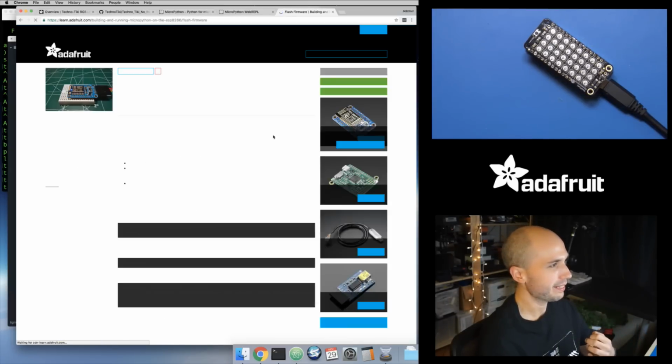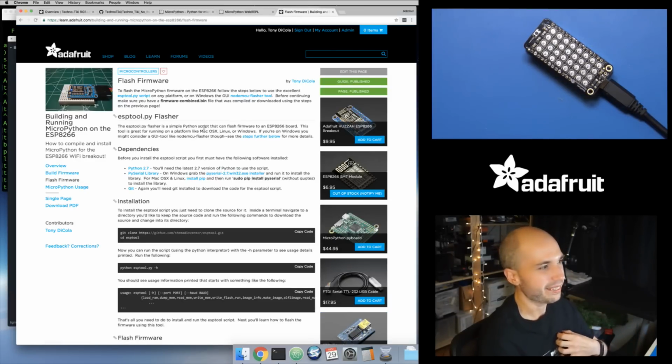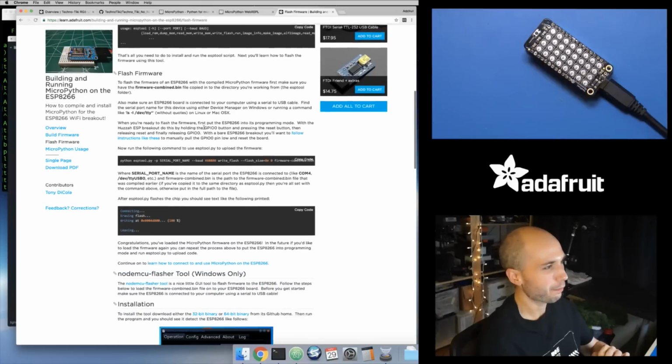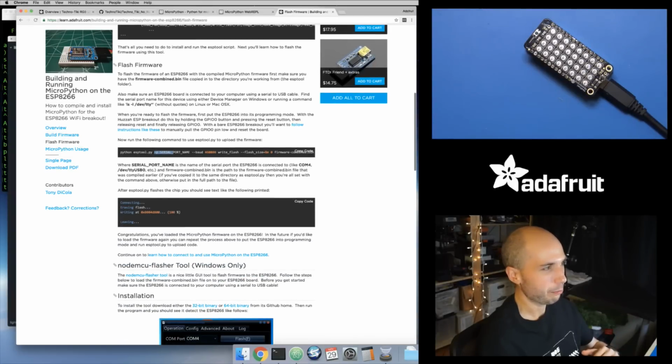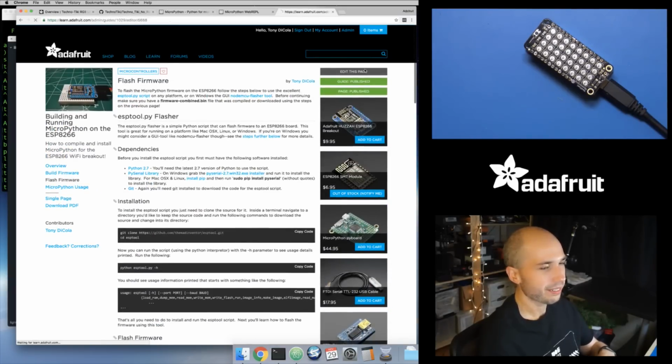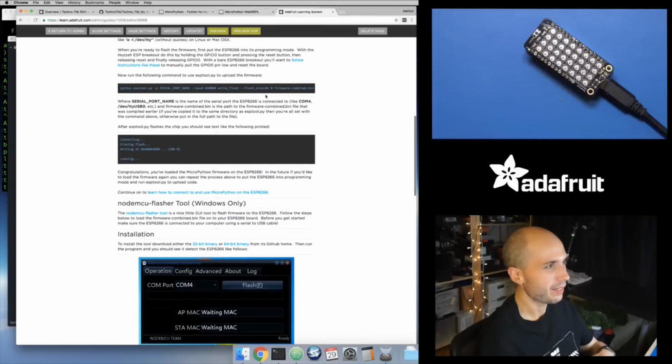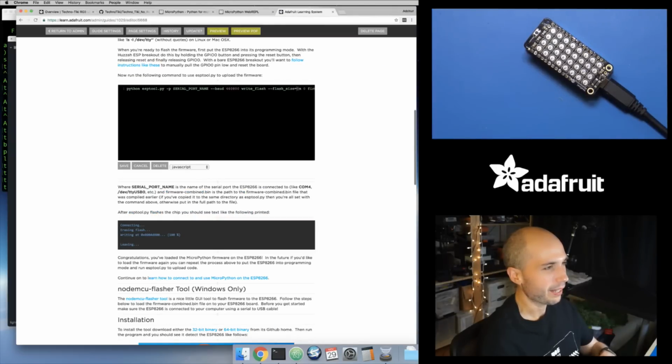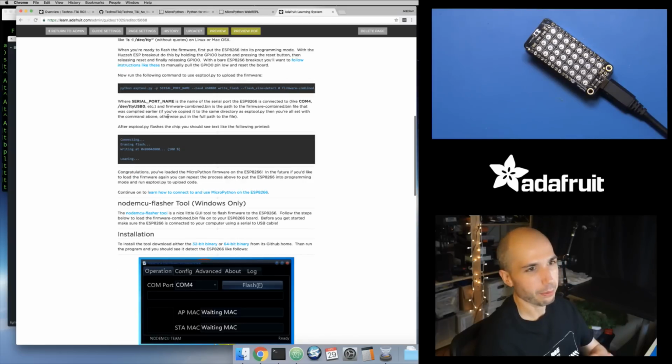And let's actually edit this guide. In this guide, I show how to flash the firmware to the ESP8266. In this parameter right here, flash_size=8M, it sounds like we actually want to set this to detect. So let's change this. This sounds like a good thing to update here, and I'll test this out right after this stream. But it sounds like this is what we want, because I always forget all these parameters and I have to search for this page myself whenever this happens. This might have been what was tripping me up before. So thank you for that tip.